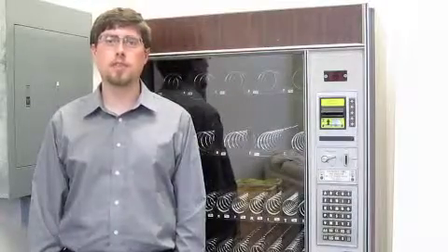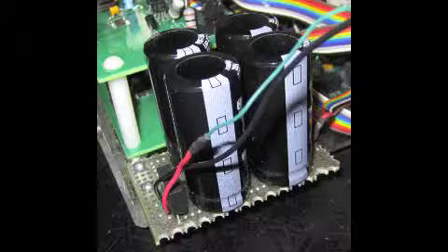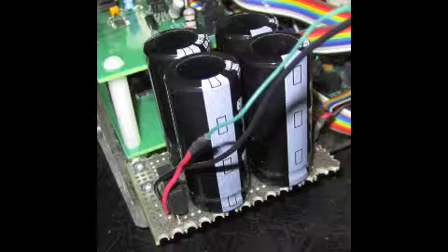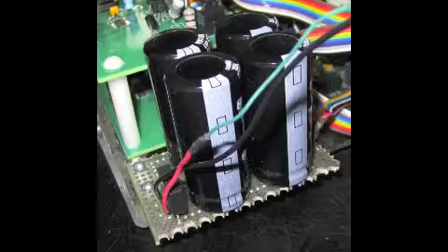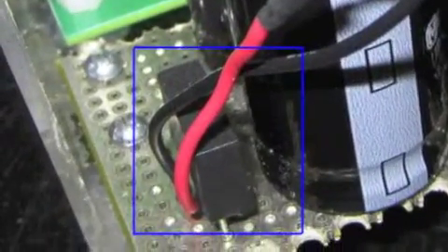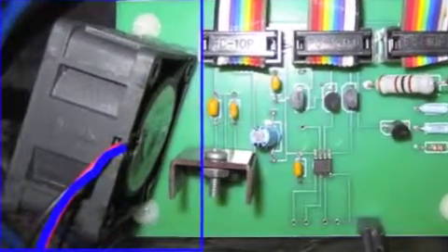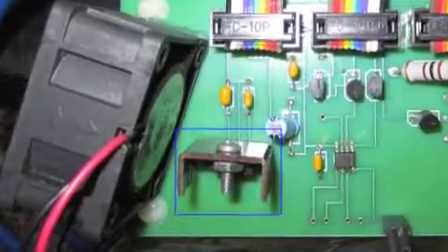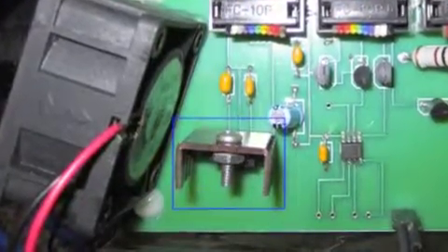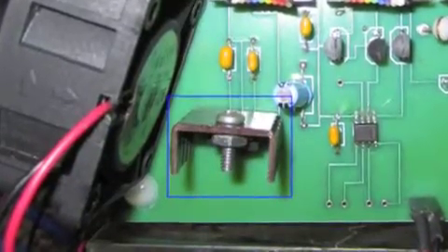This is an overview of our vending machine modifications. From the vending machine, we have a 24-volt RMS coming to a power regulator circuit which rectifies the voltage to 36 volts VDC with an appropriate ripple of 0.06 volts. This is done using a bridge rectifier. This voltage is then made available to the temperature control circuit as an unregulated voltage rail VDD, whereas two more voltage rails VCC, each at 24 volts VDC, are regulated from the 36 volt source as 1 amp voltage rails